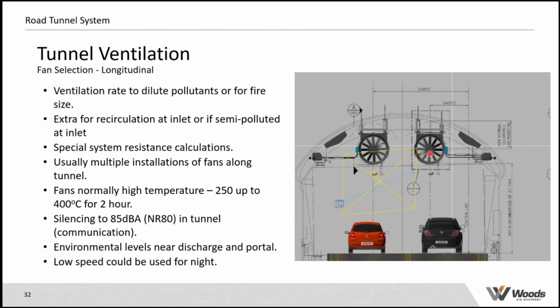they have to be spaced out throughout the tunnel, because you don't want them too close to each other longitudinally, because what can happen is that the discharge jet is effectively sucked in to the next fan further down, and it starts to offload the next jet fan. So you need a considerable distance between those fans. Typically it's 70 to 100 meters minimum distance between jet fans.